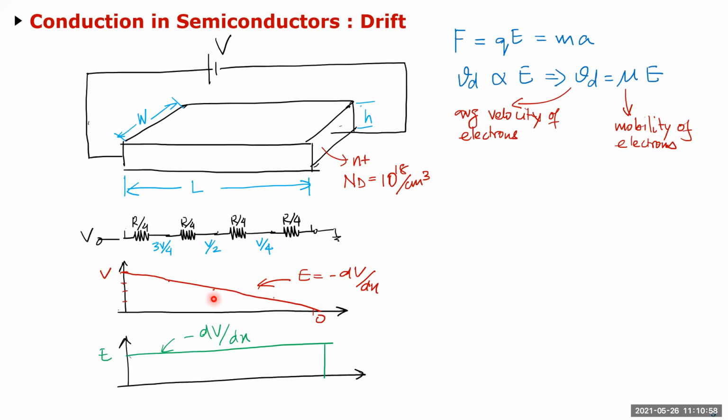I was giving an example yesterday. It's like terminal velocity, right? A skydiver dives out, he starts accelerating at g, but then the friction of the air starts increasing. At one point, the frictional force and g are the same, and that's the terminal velocity. In the semiconductor analogy, that terminal velocity is basically this Vd here, because you have a certain mobility, since the electrons are banging around depending on the lattice and type of material. You get what's called the mobility of the electrons or the holes. In the case of a p-type material, it will be the mobility of the holes.